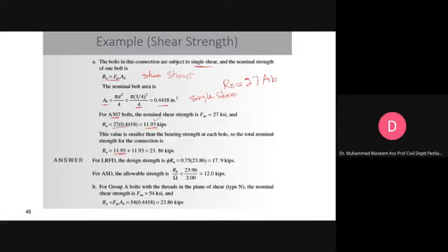Now we have two bolts in this connection. You just add them together. So the total shear strength of this connection for A307 bolt is this much. Now you have to calculate the design shear strength. Using LRFD, you will use again the same phi. Phi in this case is 0.75. For bearing case, this is still 0.75. This is phi 1. This is, let's say, phi 2. This was for the bearing. This was for the shear. This is the same. Now the factor of safety concerning ASD is the same.